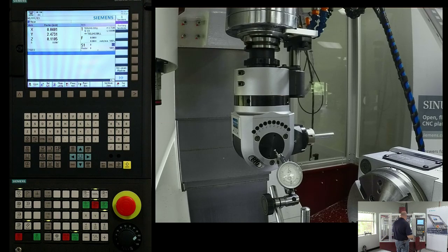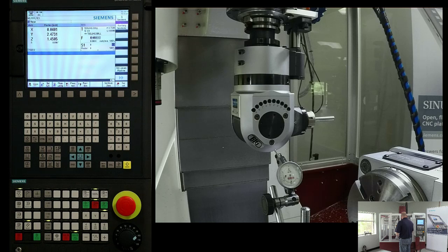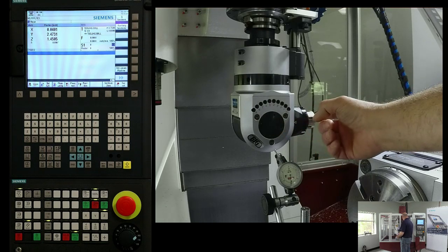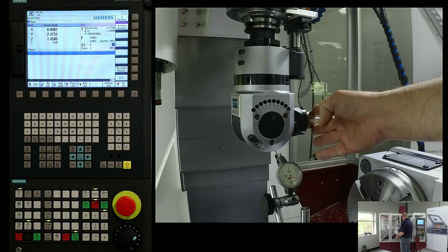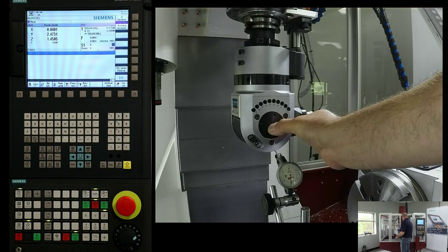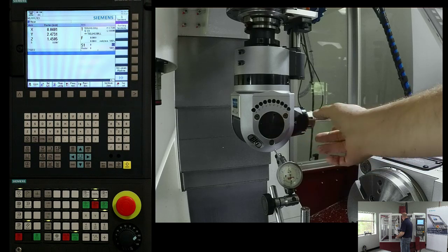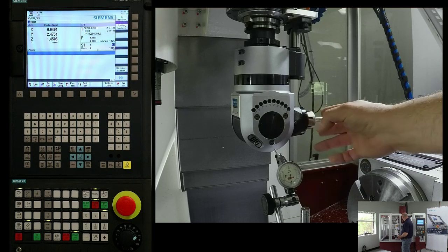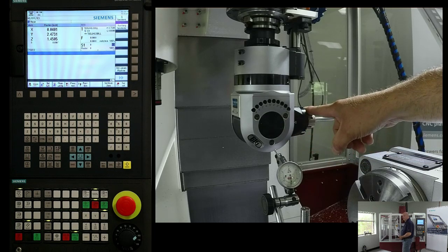That's certainly going to be the best scenario. Now the next step is, and this is going to depend on my physical head design, but I can set up a secondary value from a datum off the face of this secondary spindle to the center of rotation. Now, if I have a quick change unit, I'm going to absolutely want to do that. This one doesn't have a quick change, it's just an ER style collet.